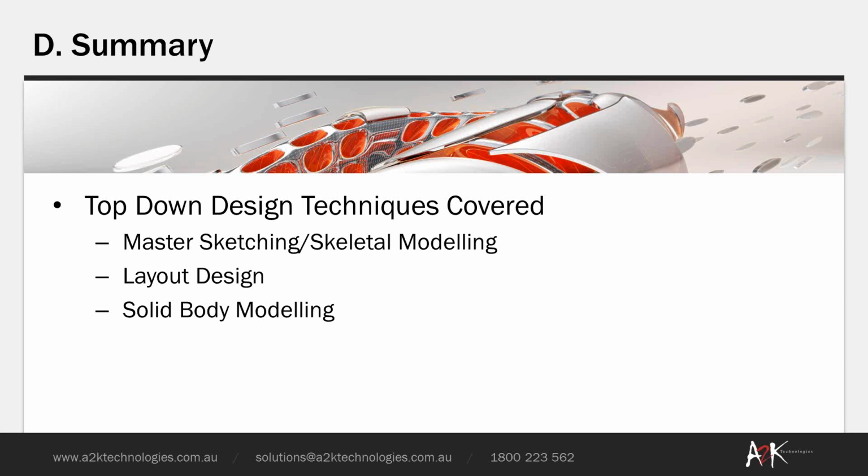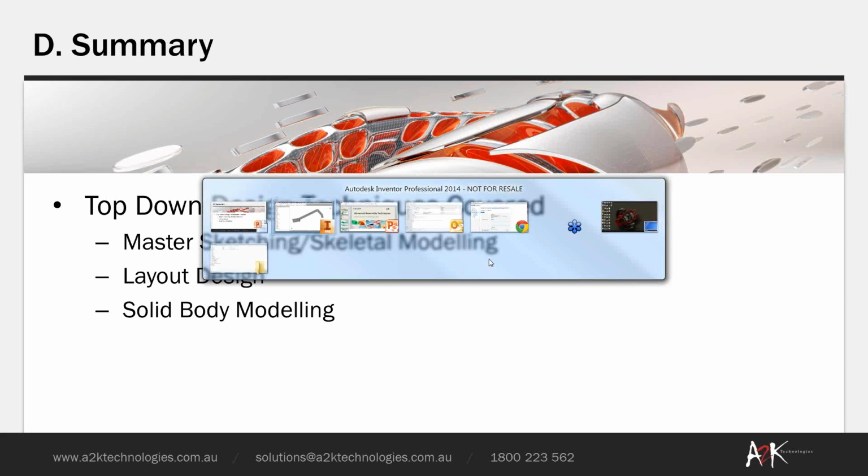And Elliot has asked, how do you offset the part from your master sketch once extruded in an assembly? So you want to offset the part at the master sketch level, I guess. So the only way you do that is by offsetting your planes. So changing your planes and changing where your sketches are. So I think that's what you're asking.